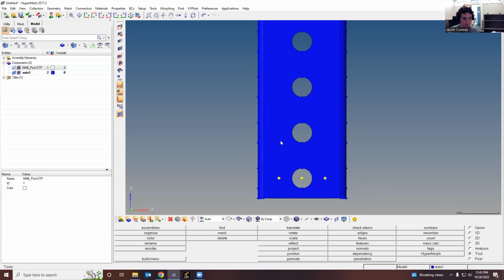And in order to get a good mesh, we want to break this, I guess I should have explained this earlier, we want to break this surface up into segments to where the auto mesh tool can't mess up really. And if it does, you can manipulate it in a few various ways to make sure that the mesh is good. And then you can just do that on one face and then rotate or move the mesh onto the other faces.